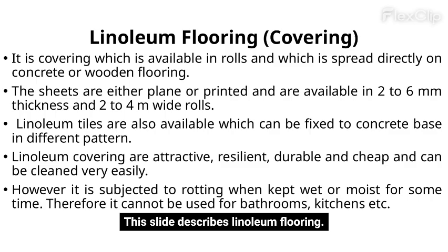This slide describes linoleum flooring. It's a covering available in rolls, spread directly on concrete or wooden flooring. It's available in sheets or tiles, in various thicknesses and widths. It's attractive, resilient, durable, cheap, and easy to clean. However, it's prone to rotting when wet, so it's unsuitable for bathrooms and kitchens.